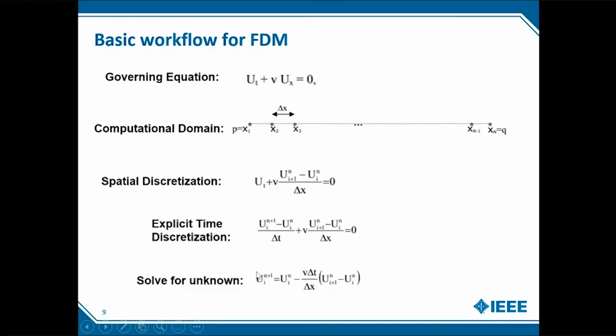And then basically this will keep on repeating until you get a converged solution. And by converged solution, I mean your ui at the current time step and ui at the next time step should have a very low error.